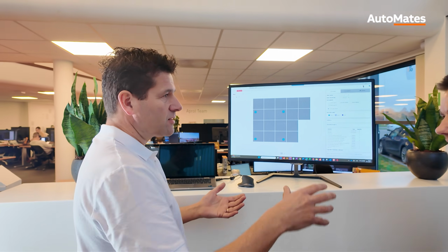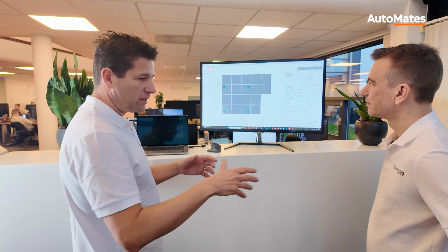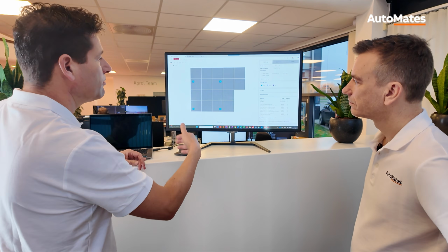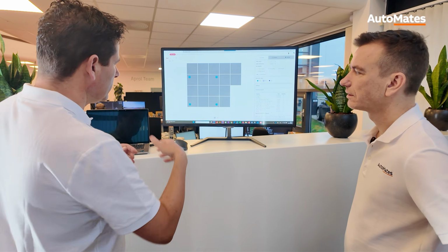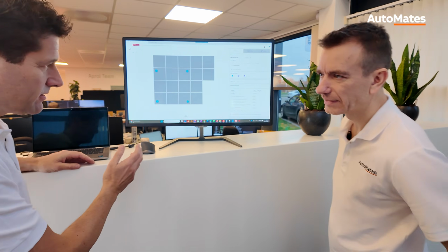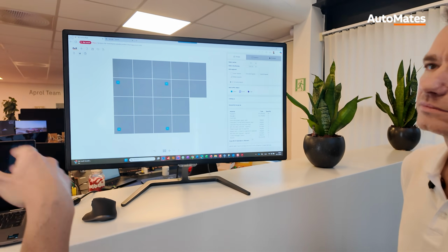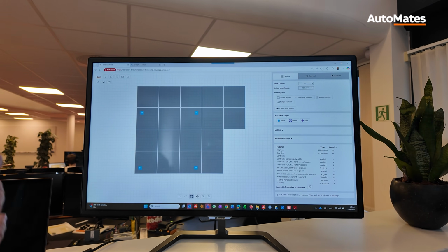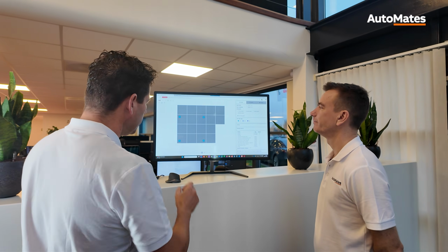And actually the whole traffic is the most difficult part. The process code is easy to imagine, but managing that there are no collisions and that the shuttles go into the correct station, depending on maybe a vision result or a measurement, that's the complex part. And that's what we manage from Traffic Manager. This tool helps to evaluate different solutions very quickly in simulation mode, but also in the end create the Traffic Manager code that runs in Automation Studio.